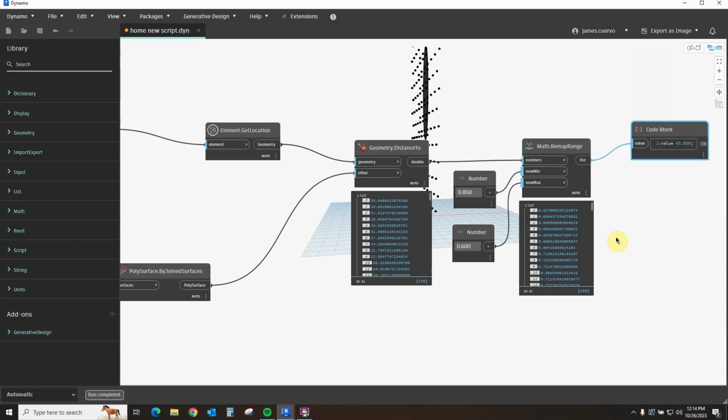So what we just did is create, with this code block, a true false list. Let's keep it open. Upon inspection of the true false list, we see that we have a lot of values that are true. There's not a lot of falses. So let's increase the amount of falses that are going to appear here. Why don't we just change this to a 7 rather than a 5 and see what happens. And now we have a lot more falses, which is actually good. We have trues and falses. This is much, much better now.